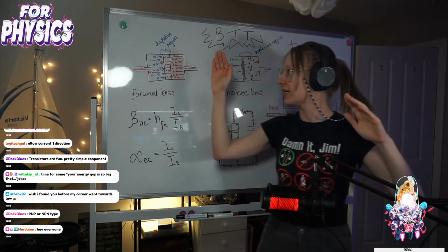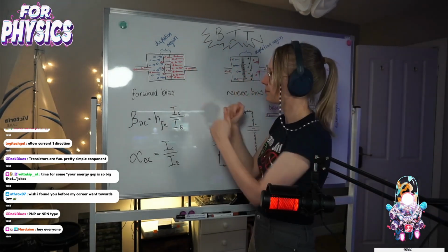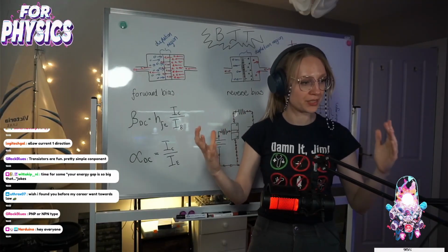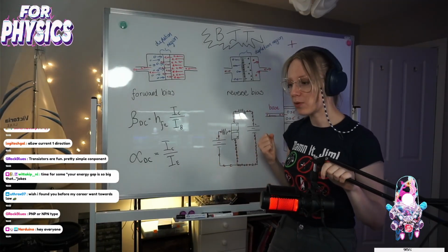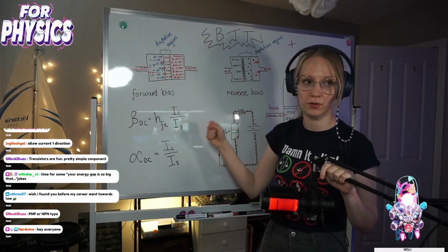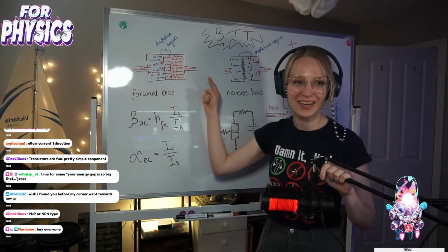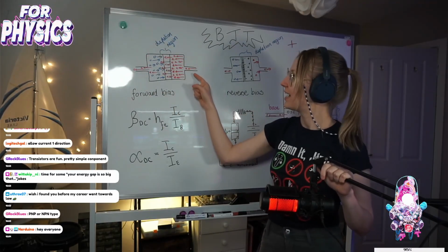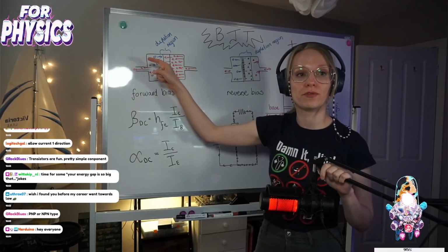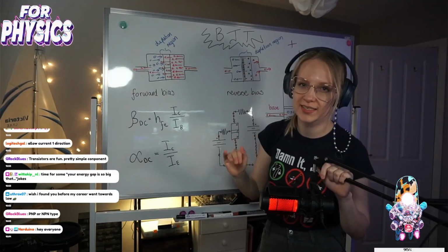So there's a net positive charge on one side and a net negative charge on the other, and so there's a huge barrier potential. This means that when we put it in a circuit in forward bias, as in we allow electron flow the correct way, in this case the current is actually that way, electron flow is this way, electrons can jump over that barrier if we meet the potential, something like 0.7 volts. This is a standard number.